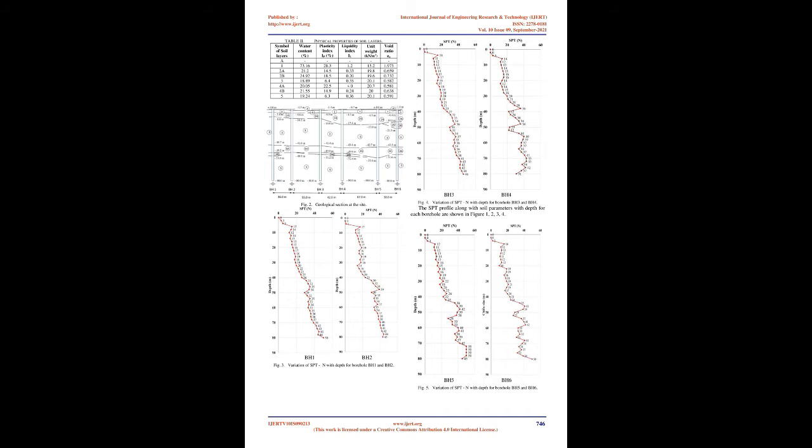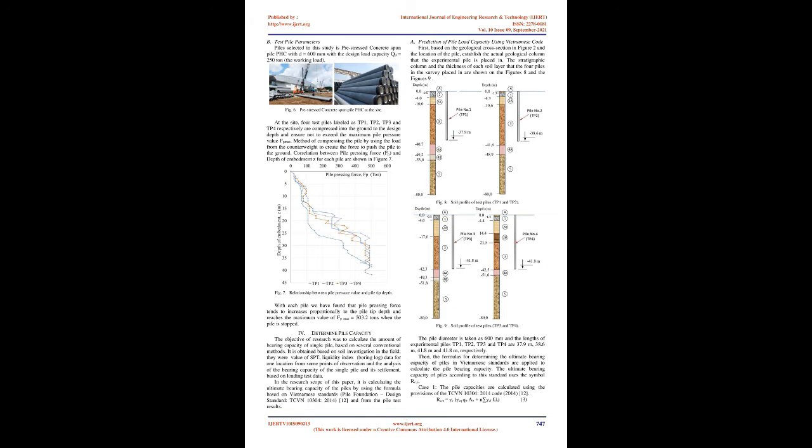Literature review. There have been many studies on predicting the bearing capacity of piles from theoretical and experimental results. These are the works of Mirza, 1997 [1], De Wacker and Pahlavi [2], Nabil [3], Brinch Hansen [4], Mazurkiewicz [5]. Mirza, 1997 [1] introduced a simple method for calculating the frictional resistance of driven piles into clay. This method is based on the correlation between the characteristic indicators and strength of soils derived from marine clay. The results show that except for the short piles in hard to very hard clay, the predictions are in agreement with the measured results at the site.